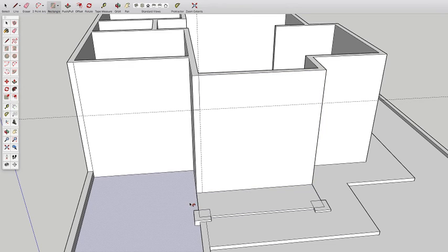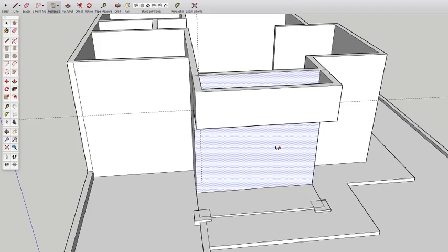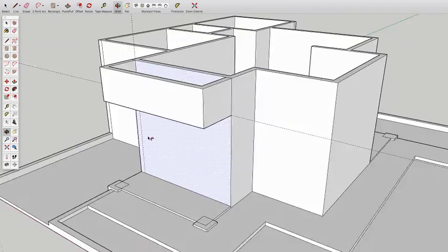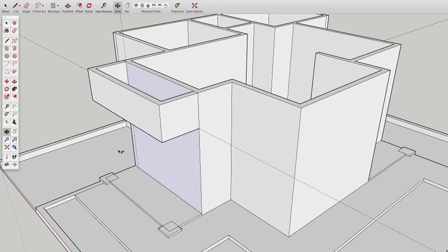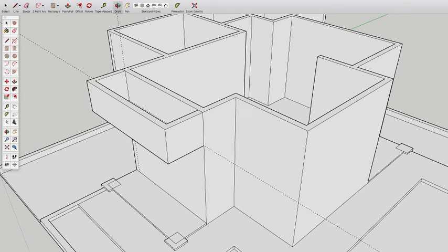When you activate your push pull tool, the guideline is not deselected, the follow me tool will recognize it, and when I hit that rectangle, it will create a wall around that selected line. Let me show you. Click it and that's it. See how this is created? Beautiful. If you manually going to do that, that will be a nightmare.